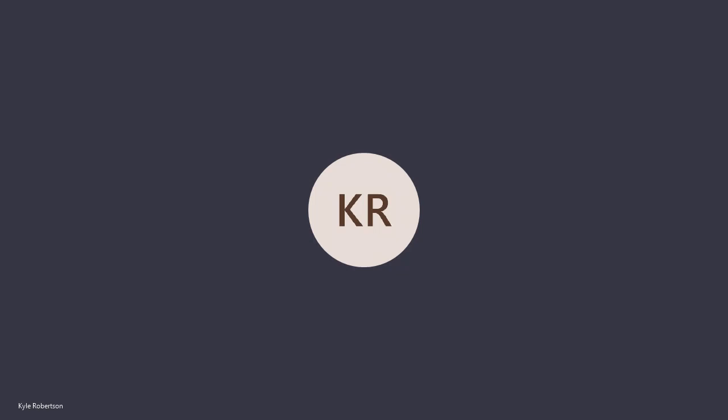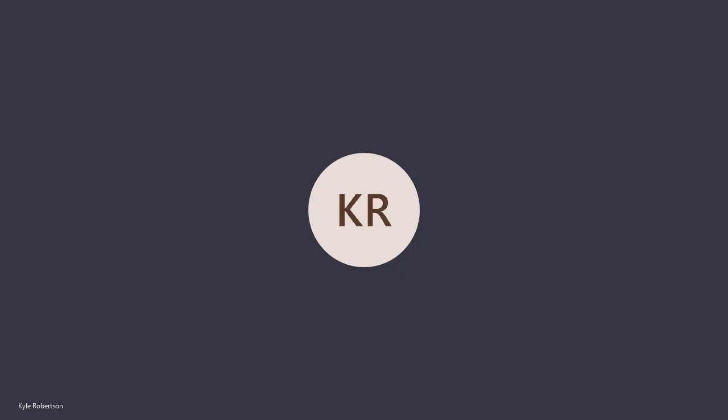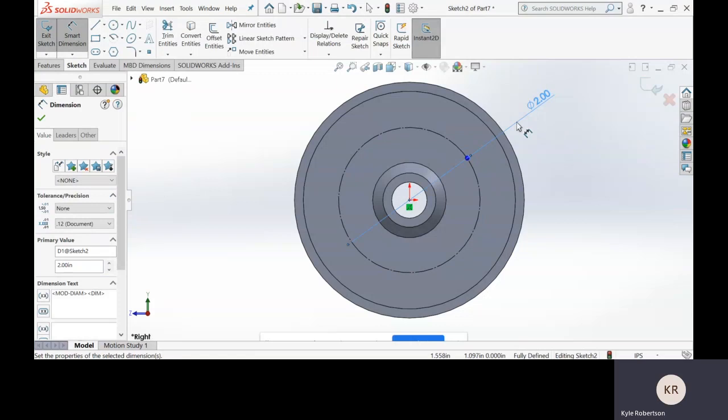If you accidentally unselected your circle, what you can do is just select the edge of the circle here and then come over here and select the for construction checkbox. That'll give us a construction circle. We know that has a distance from the center of 1 inch or a diameter of twice that, which is 2 inches. So we'll set that.